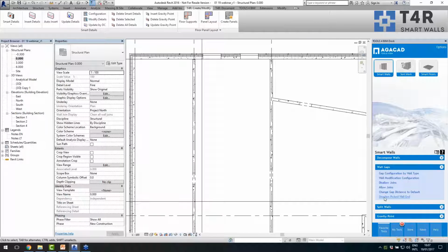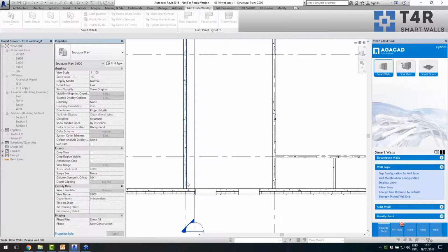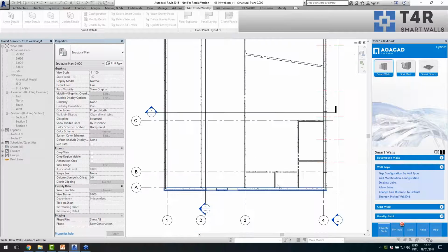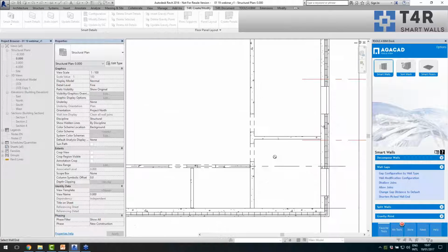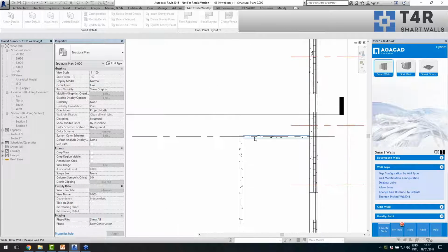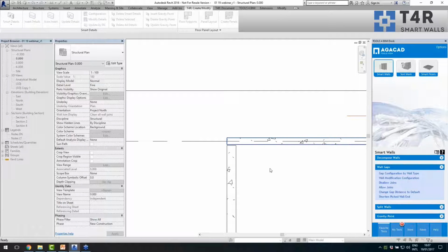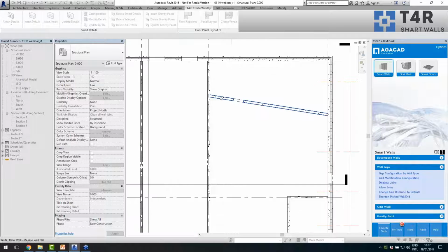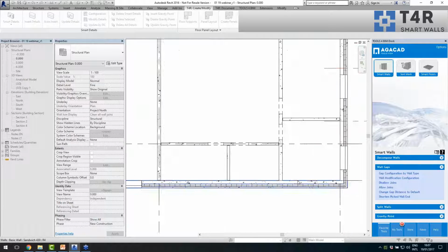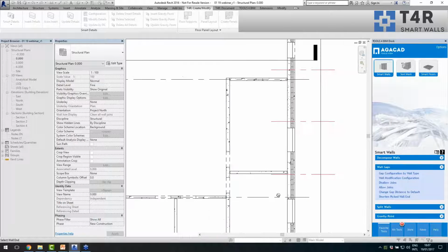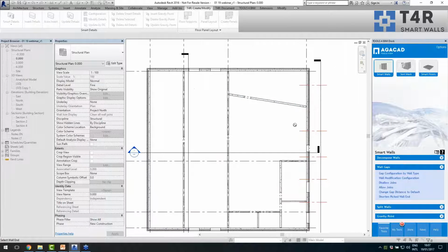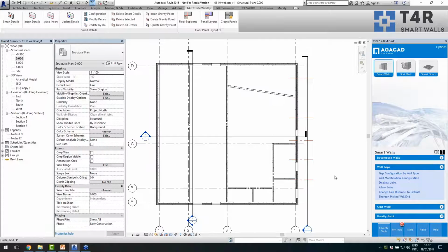Then I do the shorten picked wall command, or then I split walls. So I will do that later. Now I would like to actually just disassemble joints of these elements. Maybe I can just switch this one. Let's go around all of these walls. So I want to separate them from these adjoining elements. I want them to be panels. So first of all, I just shorten them.